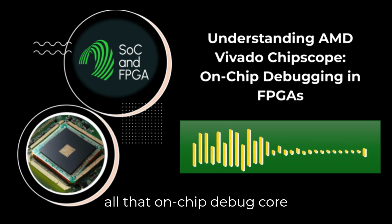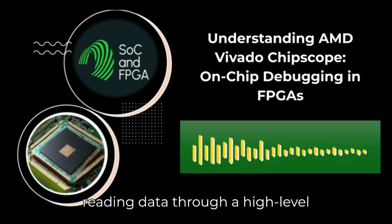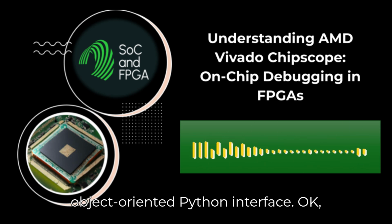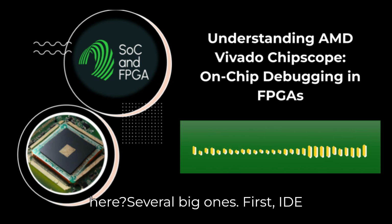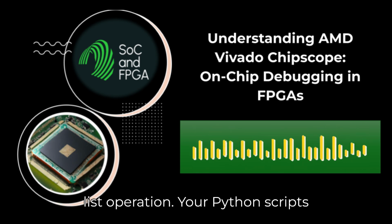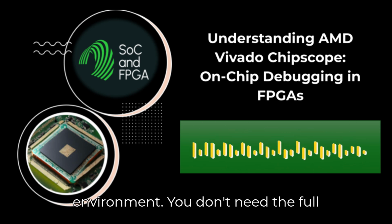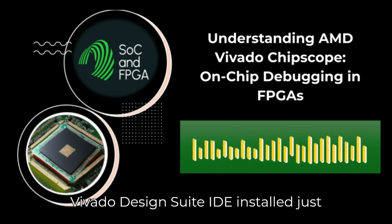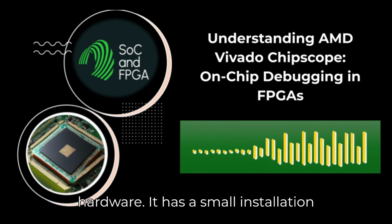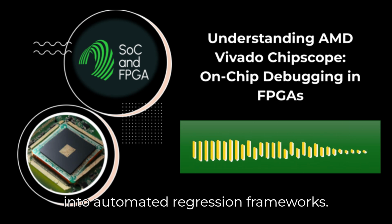Chipscope exposes all that on-chip debug core functionality controlling ILAs, VIOs, reading data through a high-level, object-oriented Python interface. Okay, what are the advantages of using Python here? Several big ones. First, IDE-less operation. Your Python scripts can run from any standard Python environment. You don't need the full Vivado Design Suite IDE installed just to interact with the debug cores on the hardware. It has a small installation footprint, making it perfect for lightweight test servers or embedding into automated regression frameworks.